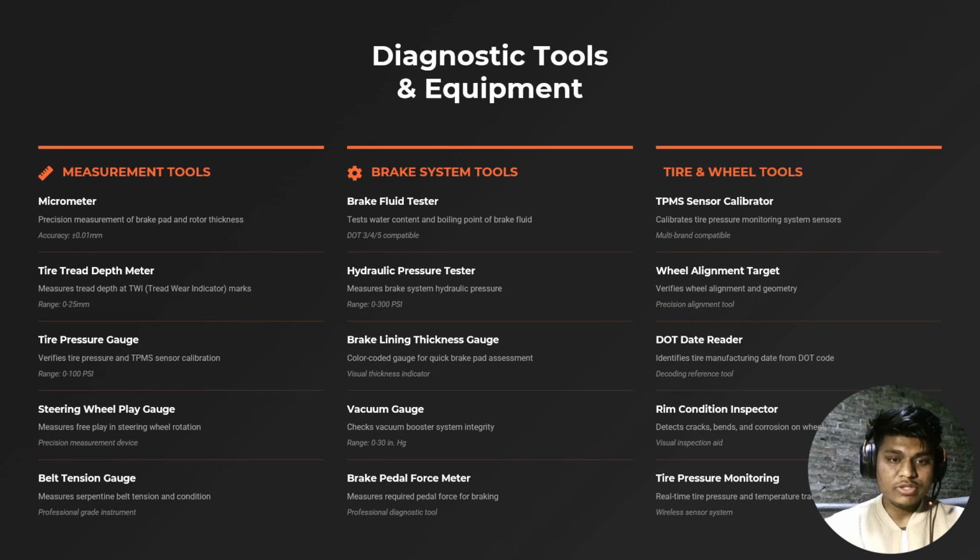To remove subjectivity, I have utilized professional grade equipment including micrometers with plus or minus 0.01 mm accuracy and brake fluid testers. I am also using belt tension gauges, TPMS calibrators, and vacuum gauges to check the booster system integrity. These instruments allow for a data-driven report that meets professional standards.